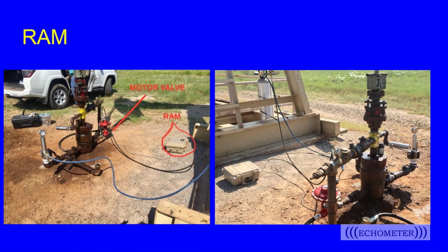We'll look more here at some examples from the fluid levels, but we're just introducing this here. In the future, we'll probably have an Echometer session on the RAM. But it's this little box. It's talking to all the sensors on the well, in this case, the gun, a pressure transducer on the well, the dynamometer sensor. And it even has the ability to control a motor valve. We're using a Kimray valve to close in the flow line. So you can open and close valves with it. You have remote control for that.